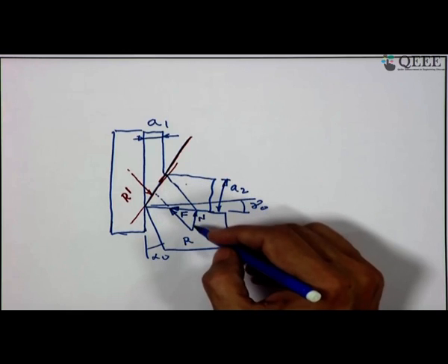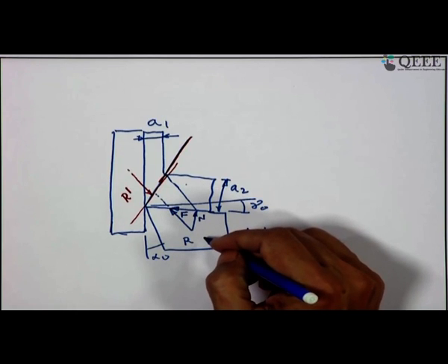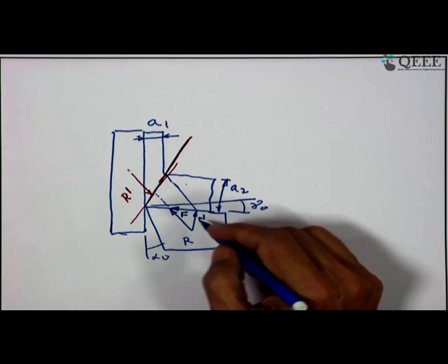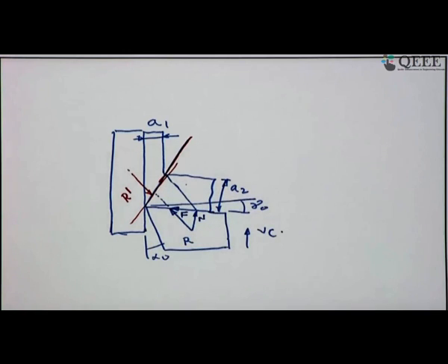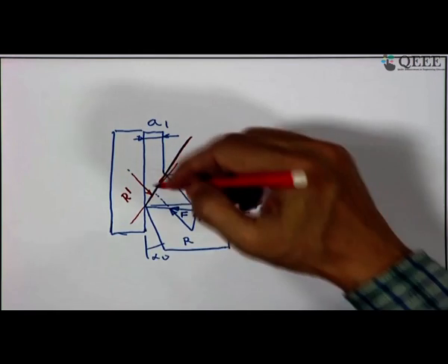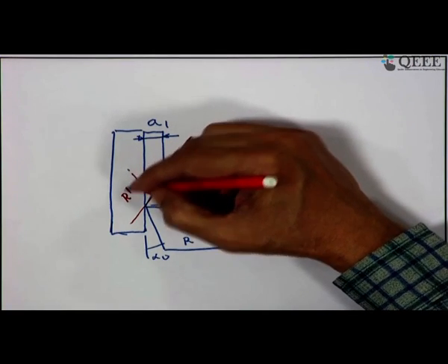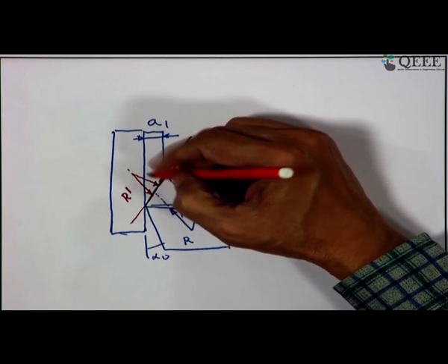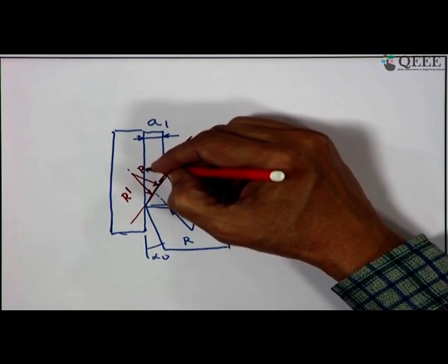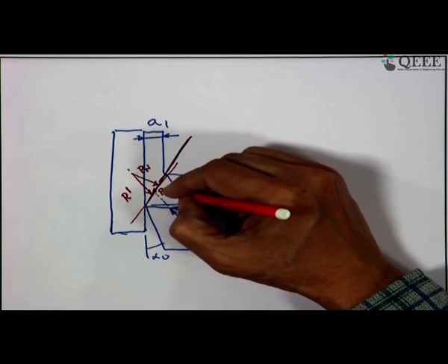Please note down or record the direction of normal force and friction force. This is exerted by the cutting tool. Now, because of R there is R dash, and from R dash also we have two components, but this is acting on the shear plane. So, we can reasonably resolve R dash into two components. One is the normal component, which we denote as Pn, another tangential component Ps.